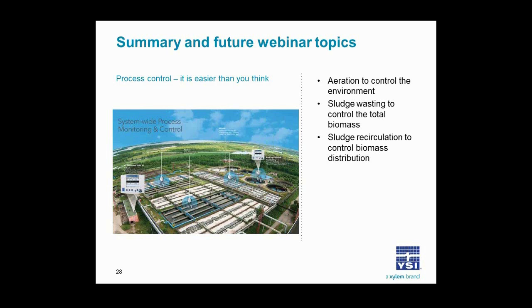So what is the quality of the sludge? It gives you a region over which you know basically it gives you a mass balance. It gives you a way to instantaneously calculate your mass balance, because within that curve, by plotting the flow rates for any condition, you can know under what condition you're operating. So, for example, the example I gave was thickening failure, where that RAS flow rate curve is outside of the flux curve.